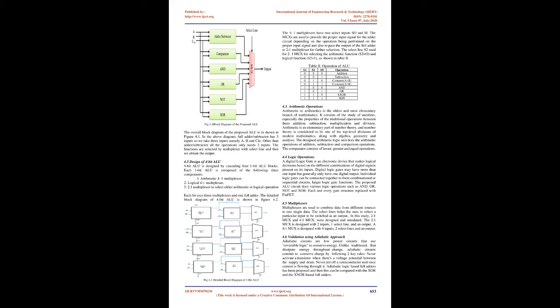3. FinFET technology. 3.1 Overview. FinFETs are quasi-planar field effect transistors. The working principle is the same as that of a planar MOSFET. Figure 3.1 shows the structure of a FinFET. The gate shells around the fin. The channel is formed perpendicular to the plane of the wafer. Its length is shown as Lg. This is the reason that the device is termed quasi-planar.